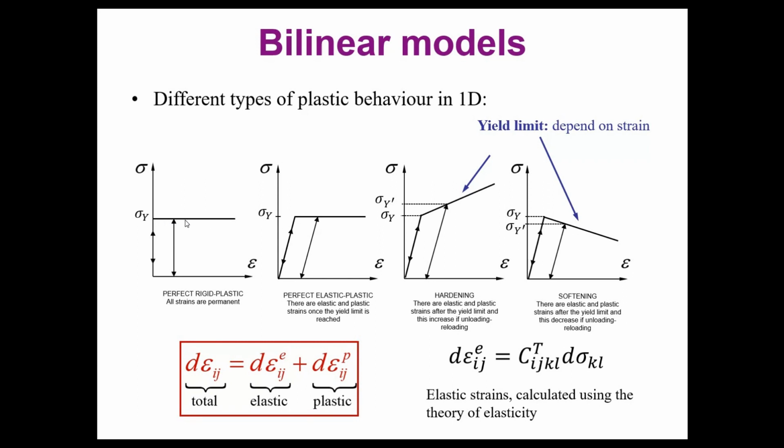So this means that you have deformation without increments in the loads. The second model is a little bit better in the sense that it's more realistic. So you have a first elastic regime where you can recover deformation because the deformation will be only elastic. And after you reach the yield limit and you go farther, you will have plastic deformations, but parts of the deformation will be elastic. So you have the possibility to recover at least parts of the total deformation you have in your structure.